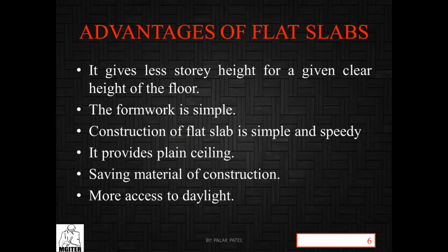Now we have some advantages of flat slab. The first advantage is a lesser storey height for the given clear height of the floor. Formwork is simple because there is no beam; you just have to provide flat plates. Construction of a flat slab is simple and speedy. There is a plain ceiling area because there is no beam, saving materials and giving more access to daylight, right?